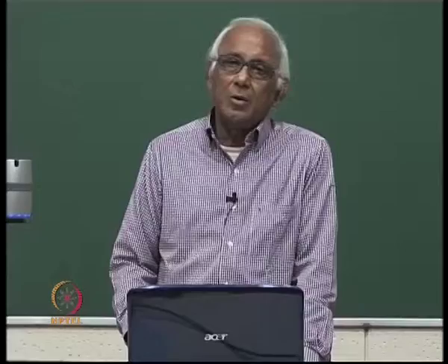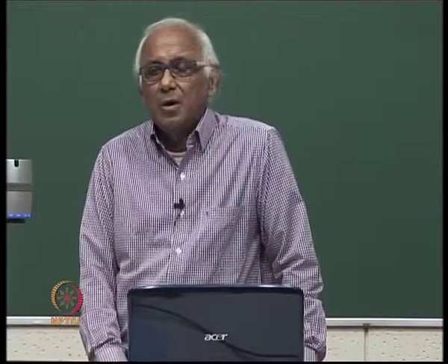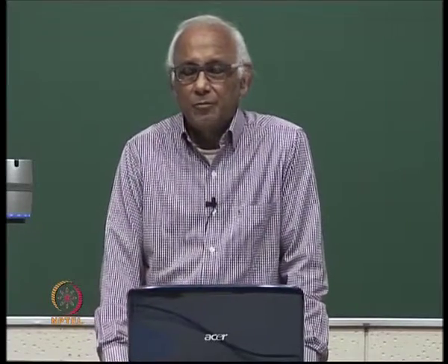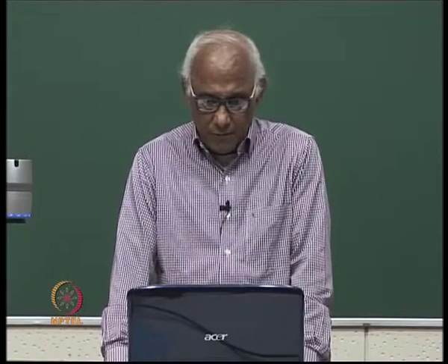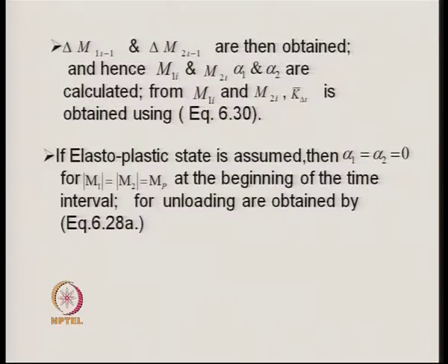So, in this particular way one can find out the total stiffness of the system at any increment of time delta t, and with the help of that stiffness we calculate the incremental displacement, that is displacement and rotations for the system for the incremental loading.